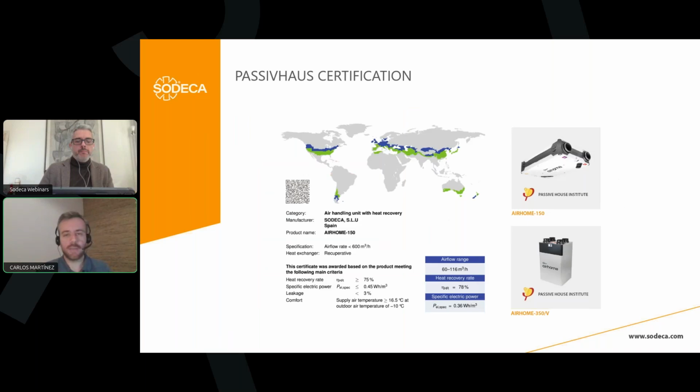So in SODECA, we have 2 pieces of equipment certified for Passive House compliance. It is not mandatory to have this certification, okay? It is mandatory to have a heat recovery unit in the project, but it is not mandatory that the heat recovery unit is certified by Passive House. But the performance declared by us, by the manufacturer, is reduced by 12% if the unit is not Passivhaus certified.